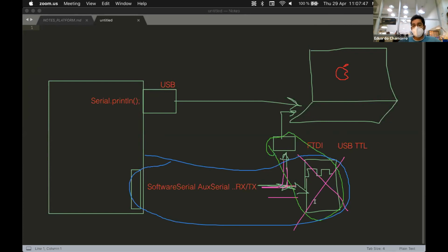Usually for configuring this kind of devices, if they are made to work out of the box, most of them use something called AT commands. That is a super basic set of instructions to configure different baud rates, different speeds of communication, the clock frequency. Like configuring the basic setup of the board, but not the main program itself. It is widely used for Bluetooth modules, Wi-Fi modules, radio modules, especially for wireless communication, but some devices that are not just for wireless also use AT commands.